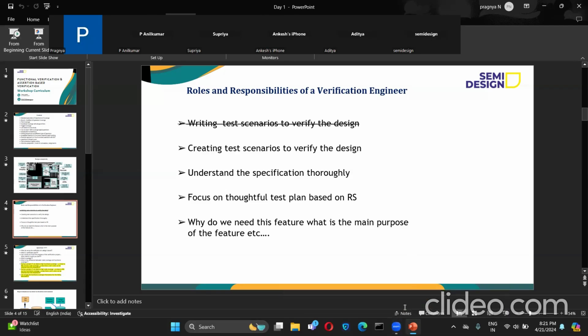For getting more into the verification, we can do assertion-based verification, where it will test the functionality, whether our DUT has the functionality passing or not. If we give the assertions, it will show immediately the failure of the functionality. And for the functional verification, we create coverage bins. Coverage bins can show that all the functions are covered or not. And the code coverage further shows how efficient our test bench is.